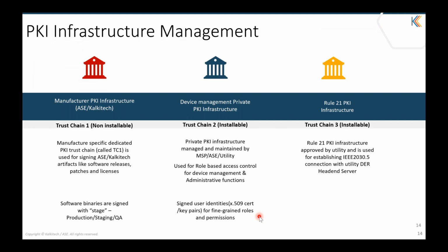There are two ways a user access check is done. It is using OCSP-based validation, or else there is one more option, per IEEE 62351-8, that is the attribute certificate based permission validation. Either of these two options can be enabled, and it helps the network admin ensure that only users who have been allotted privileged access or access permissions can access the device and do any operations.